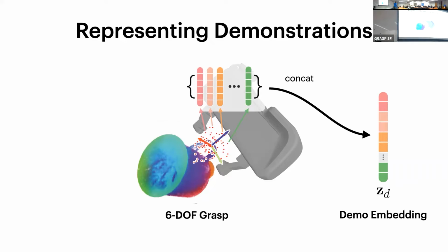So basically this is a feature field, it's a 3D model of the scene. The camera is mounted on the selfie stick. At the beginning of this session, the robot picks up the selfie stick, does a scan and collects like 50 images. And then we do structure from motion for all of the images to get the camera poses. And that allows us to produce this feature field. So the robot scans once, builds this model.